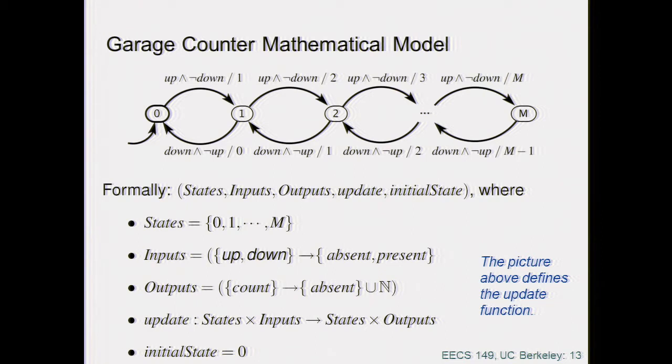Which, in principle, and should always be so, is a different function than the next state function. Sometimes they can be merged, as we said before. For example, in the case in which I can encode the states with the output, then it's the same, right? That doesn't make any difference. But in general, it's not the case. So from states cross inputs, you go to states cross outputs.